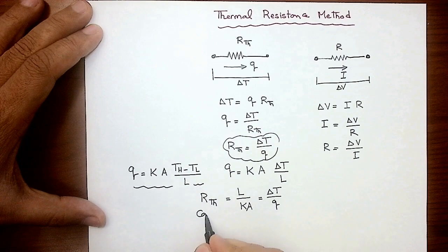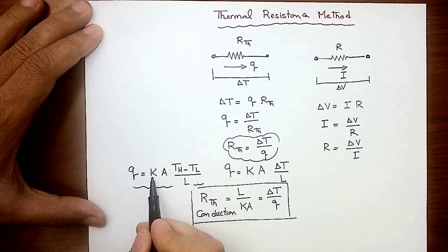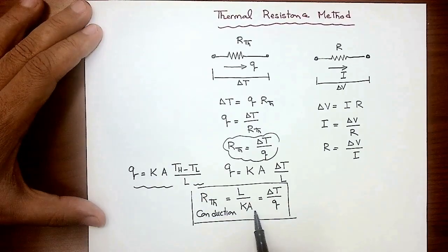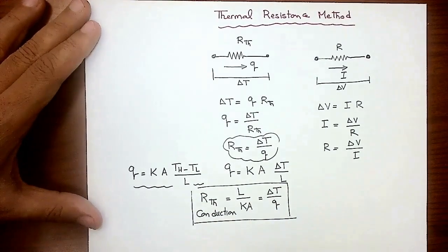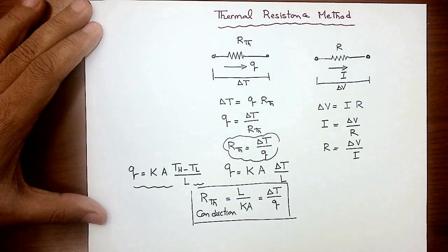That's a conduction. So thermal resistance of a conduction can be defined as the thickness of the wall, L, remember, divided by the thermal conductivity times A, which is A perpendicular to that Q. So now I can calculate a thermal resistance that's present in a single wall.